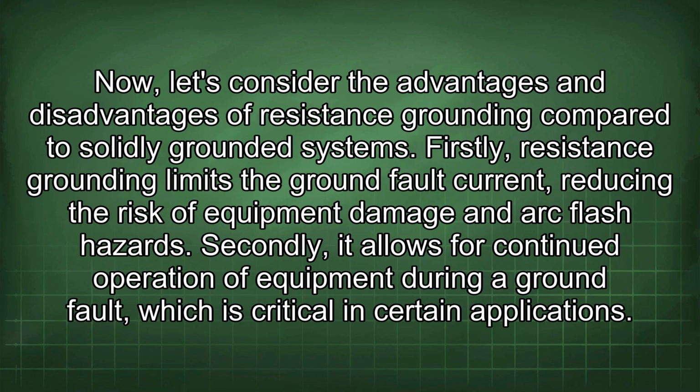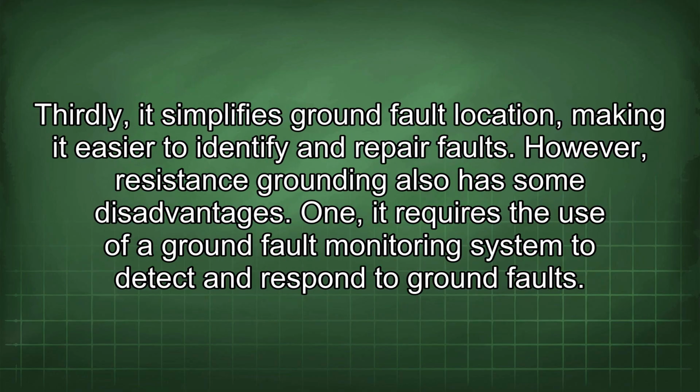Now, let's consider the advantages and disadvantages of resistance grounding compared to solidly grounded systems. Firstly, resistance grounding limits the ground fault current, reducing the risk of equipment damage and arc flash hazards. Secondly, it allows for continued operation of equipment during a ground fault, which is critical in certain applications. Thirdly, it simplifies ground fault location, making it easier to identify and repair faults.